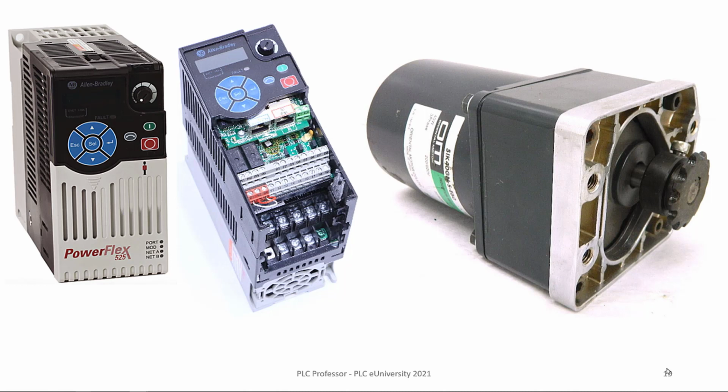They're gray, and then there's three that are orange, the safety. Well, you can do 2-wire, 3-wire, and other methods of control. You can also hook up an external potentiometer for speed control, or you can have an analog output from the PLC that wires in here for speed control, or up underneath the faceplate, the 4 blue buttons with one in the center.